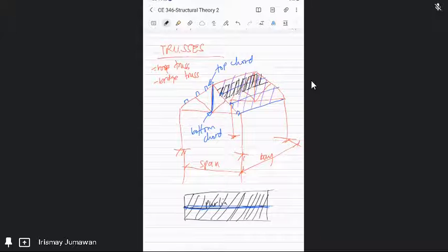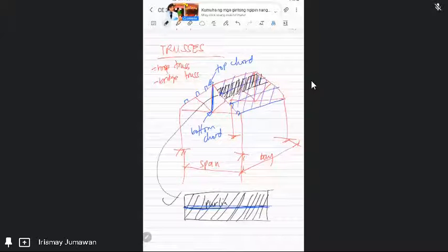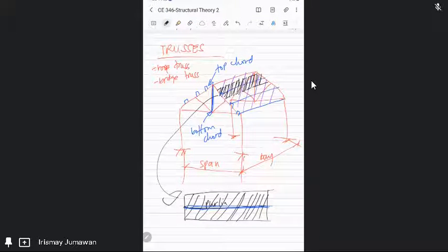No, that is not the span. The spacing: one half of the spacing of your purlins, which I shaded here, will be taken as the tributary area for your loading. If your spacing is equal, then it is equal on both sides, half on one side and half on the other, the same as the width of your division.